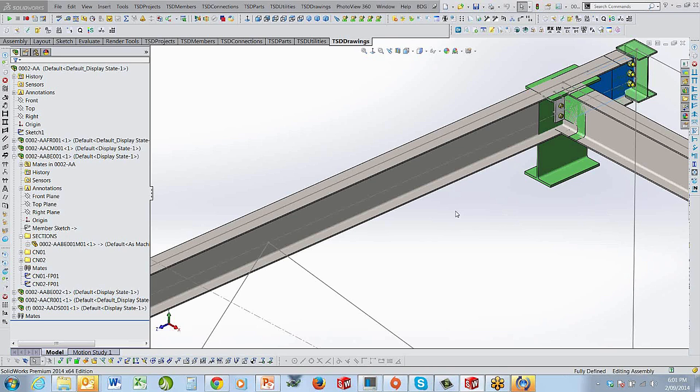And I'm sure that if you did work in your office and you had another guy in your office and they were going to pick up your project, the naming and everything is the exact same. So there's a lot of logic behind why this has been done. We have a 12-digit maximum code. Some CNC machines, which we're working towards for DSTV, only have a certain number of characters that you can use to inscribe onto sections, and that all depends on what machine you're using. So we've got 12 digits as our maximum. We don't want to venture any further than that, and the code that we've got seems to work quite well.